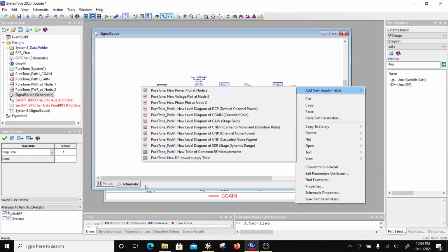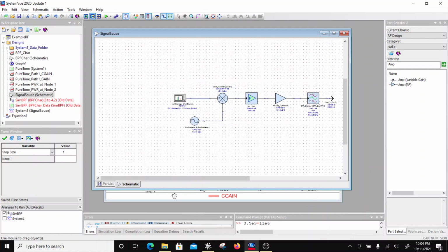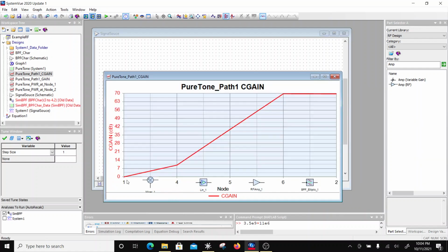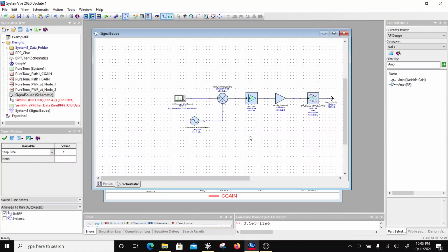Okay, I guess you have to look at it in terms of gain compression. So at minus 50, the mixer is 0.1 dB compressed, and for the PA, over here it is 39.9, so this will be 69.9. So this amplifier is 2.2 dB compressed, the mixer is 0.1 dB compressed, and the other two blocks will be unaffected.